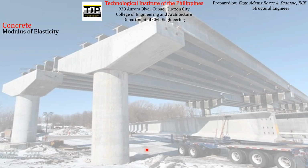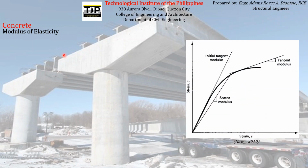So next, related to the properties of hardened concrete as well is the modulus of elasticity. Actually, this is the one that we usually use to measure the stiffness of the concrete. So actually, modulus of elasticity is somehow related to the stress strain curve. So again, we have here another stress strain curve. The horizontal axis is the strain, the vertical axis is the stress, and this is some part of the stress strain curve of a concrete.